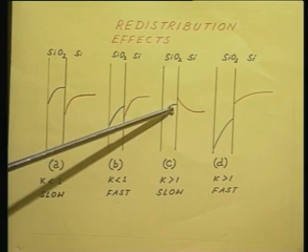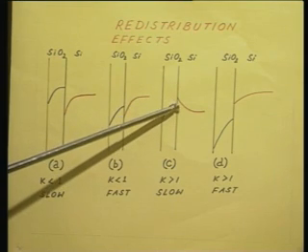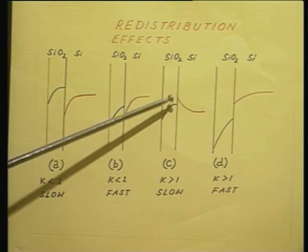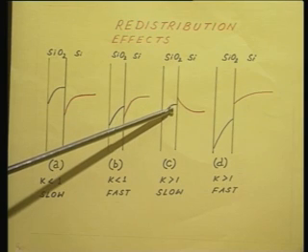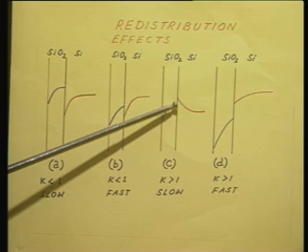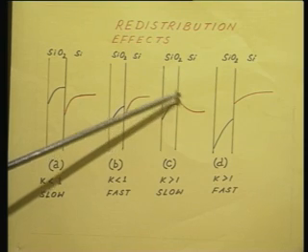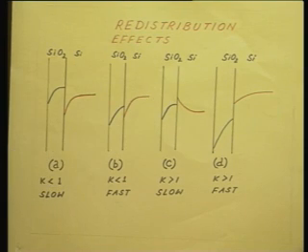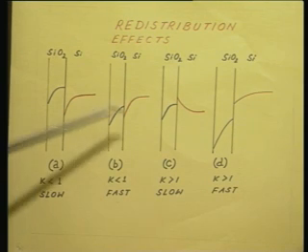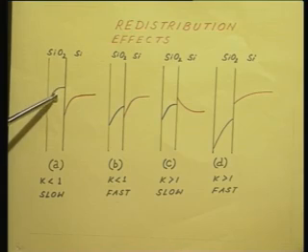On the silicon dioxide side you notice that at the interface the concentration of phosphorus is less on the silicon dioxide side. This black line starts at a level lower than the red line at the interface, right. And phosphorus is a slow diffuser in the oxide. Therefore, the profile of phosphorus in the oxide is also going to be somewhat similar to this.